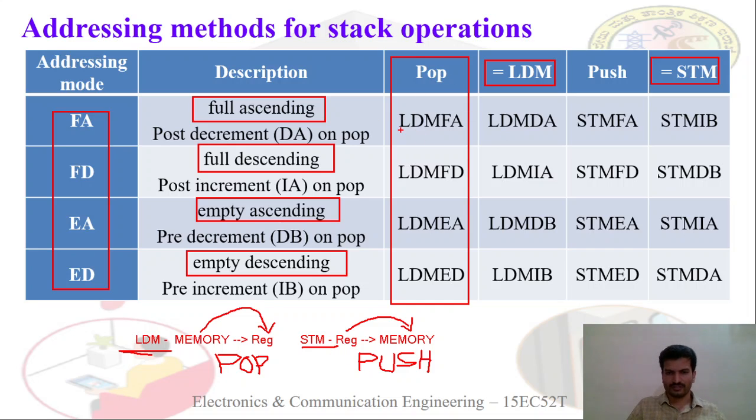Here for the pop operation we are using the LDM instruction, and we need to specify the addressing mode. So LDMFA, LDMFD, LDMEA, LDMED. These are the instructions which are equivalent to the LDM instruction. So LDMFA is equal to LDMDB.